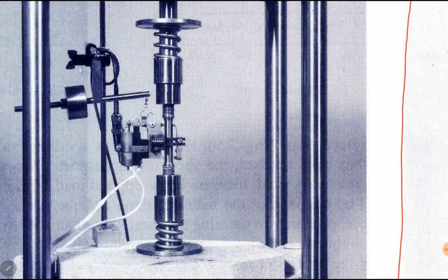The atoms are usually bonded together. When we disturb them and apply force on them, they resist the external forces, resist the deformation. This resistance is actually stress. After the upper yield point, there is a change in the internal structure, the equilibrium of the internal structure. The layers of the atoms slip upon each other. This slip gives rise to another state of equilibrium. The atomic structure goes from one state of equilibrium to another state of equilibrium.